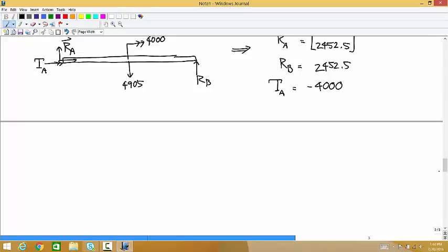Okay, so now for the cuts. N is equal to 3, so we're going to have to make 2 cuts. You have the 2 endpoints, and then the only other things going on are at that midpoint. If more than one thing is acting at the same point, you just want the internal. All you care about is the point, not whether that point is represented or not.